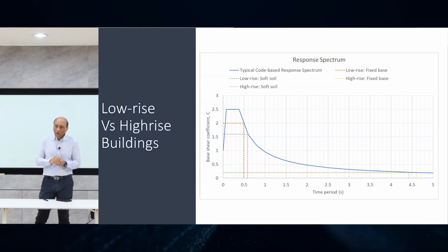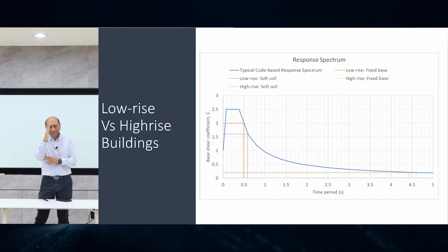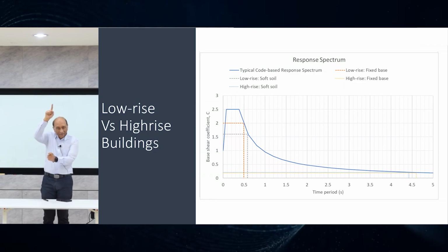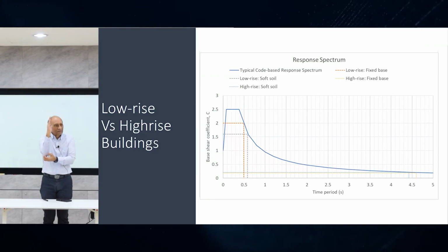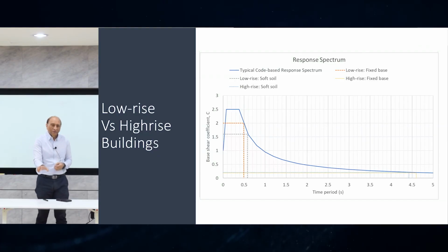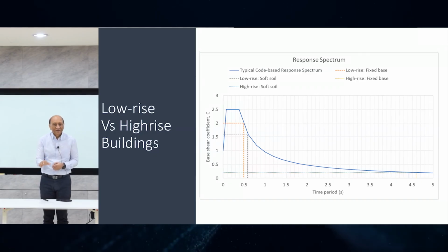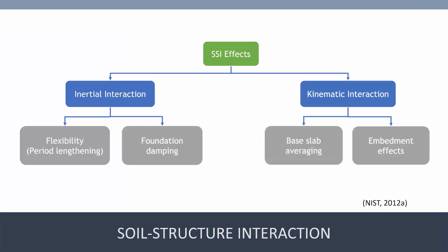But it will change a lot in terms of the tilt of the building and the drift of the building and stability of the building, because a small rotation at the base will amplify by a huge height, and then you can see even one small half a radian, a little bit. This one, the top will sway a lot. So if you model the soil, you will find the natural period may not change, but this drift and sway will change a lot. Deflection will change a lot. So now let's get into more detail.